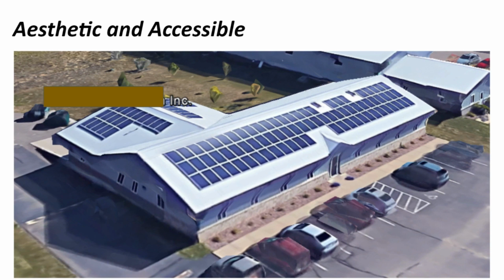One of the more important decisions of solar design is considering rooftop accessibility, as slanted roofs are not designed to be accessible places. But with a solar array located on the roof, that roof surface will inevitably need someone back up on it for array servicing at some point in the near or distant future.